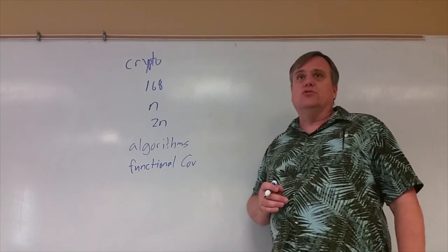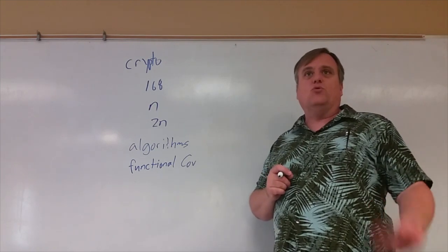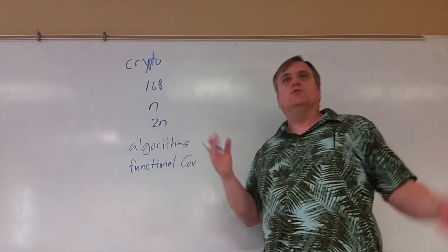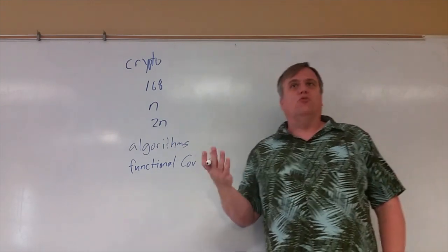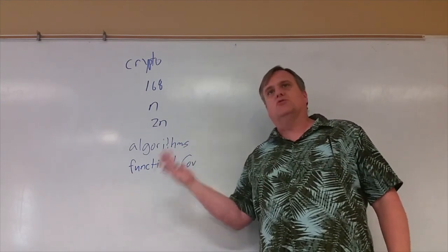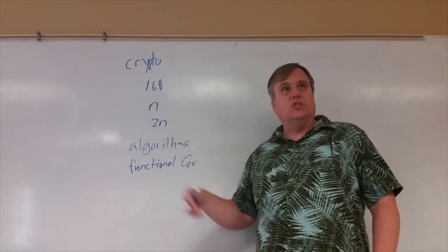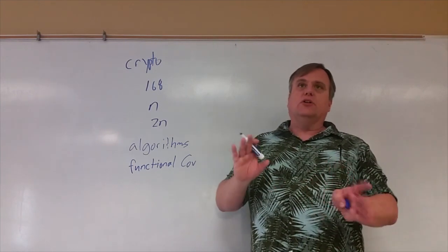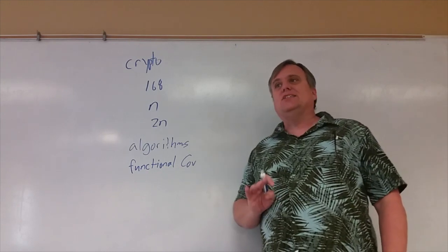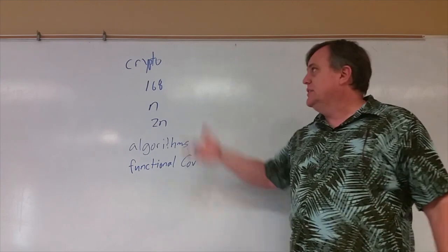You'll notice that in addition to urandom, there's also random. And some people ask, what's the difference? Random stinks. That's the difference. So you should never use it. Random was the original, and urandom was put in to fix the problems because it wasn't actually random. When you started doing functional coverage and other areas that you would select within your test, random did not work well. So it still exists for legacy, but it's deprecated, and it's deprecated because of exactly this: it stinks at it.